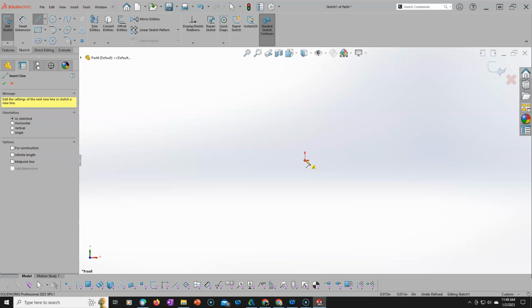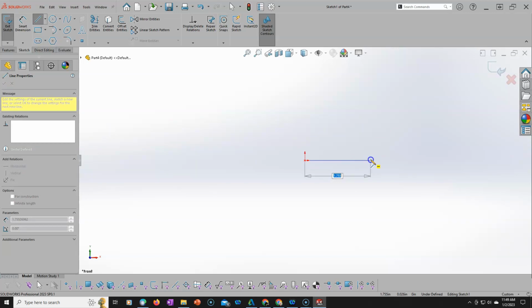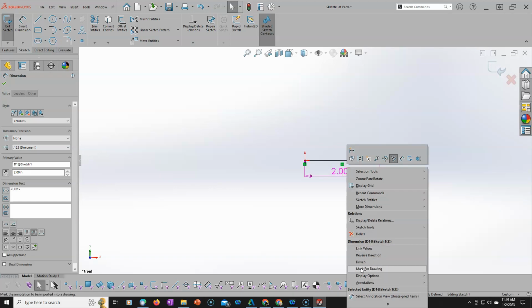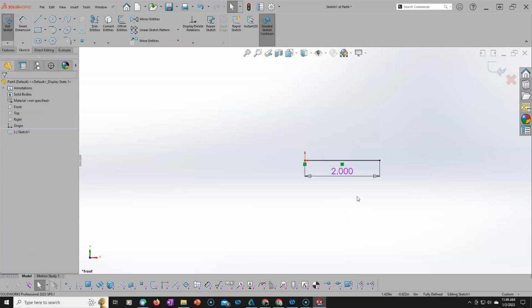90% of the time, in the videos, you're going to see me click drag. So I'll start with that. Left click, hold down, and drag. Now my sketch numeric input is on, and I'm in Windows 10, and I have it set for this value. So if I were to put in 2 inches and hit enter, then I'm going to apply that dimension to the line. Difference being that from what I've seen in 2011, and maybe somebody can verify this for me, if I right click, the driven will be selected. And I'm not sure why it's automatically going to driven, and not sure where those parameters are.